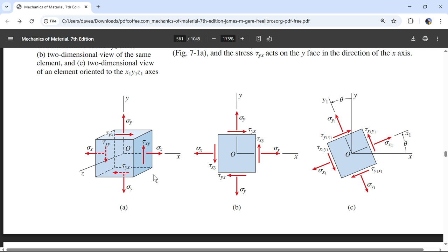So that's what the free body diagram would look like. I would have a force down, a force to the left. I would have a force up right here and a force over that are going to be smaller. And then because I have a cut, I'm going to have a normal force in this direction that's normal to the surface of the cut, and then a shear force. If you just put the convention that it's going to rotate this way, cool, whatever.